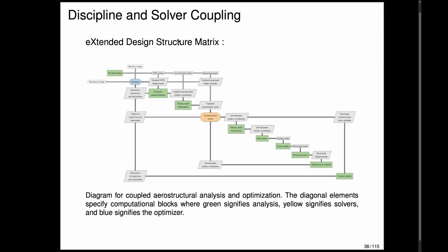In this case, we do it sequentially. We use a Block-Gauss-Seidel method to first compute the aero side, then project it to the structure, and then update aero, update structure, and so on. So the solvers aren't coupled internally, but they're coupled with OpenMDAO, and using a Block-Gauss-Seidel method will iterate to converge the two. Okay, thanks. Does that make sense? Yes.